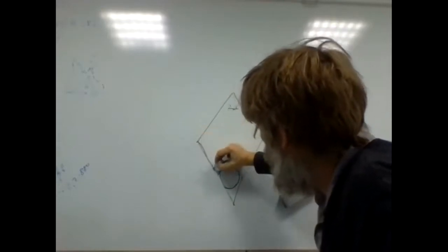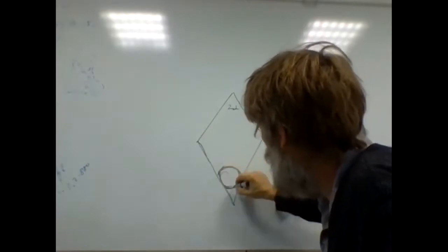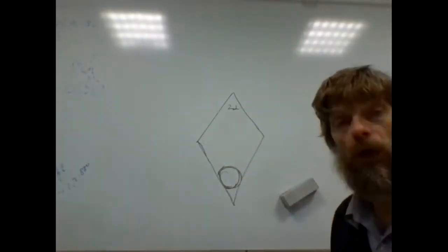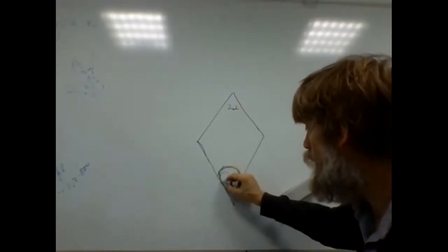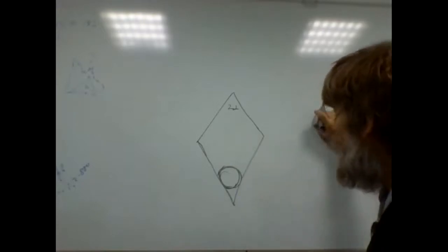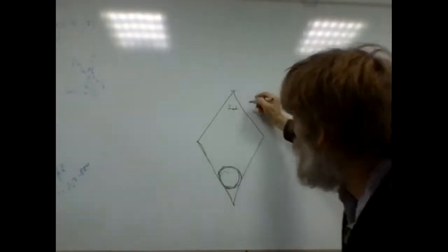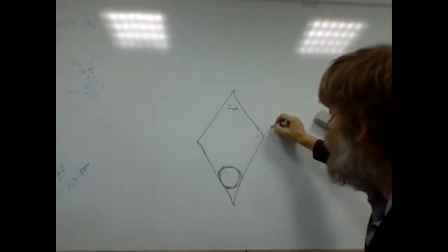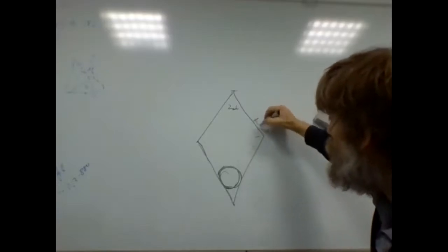Now we need to consider equilibrium. Perhaps the most difficult task here is to figure out the equilibrium for this rod here, or this rod here. First thing is that because this is hinged, it can freely rotate here, and because of that, tension T here is along the rod.